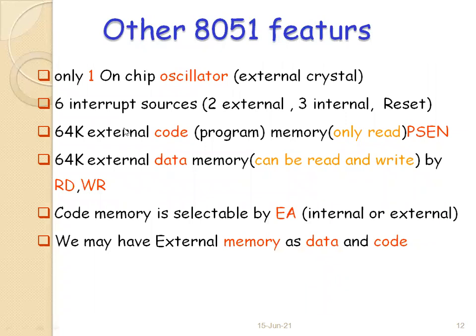The other 8051 features: it has only one on-chip oscillator, with an external oscillator option. It has 6 interrupt sources, which will be discussed in subsequent lessons: 2 external interrupts, 3 internal interrupts, and reset as the 1 remaining interrupt.